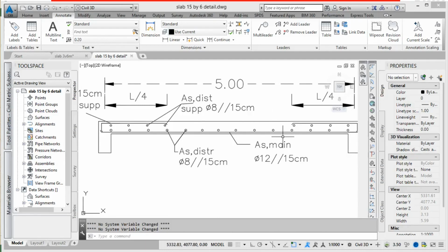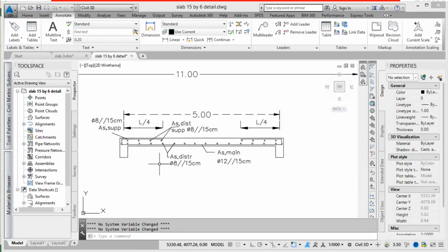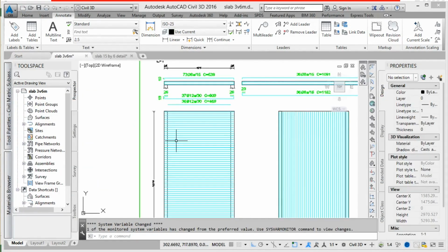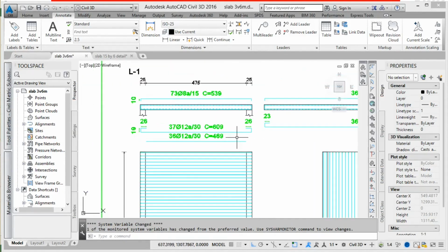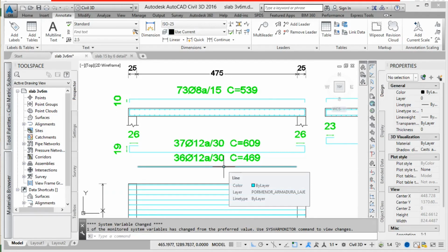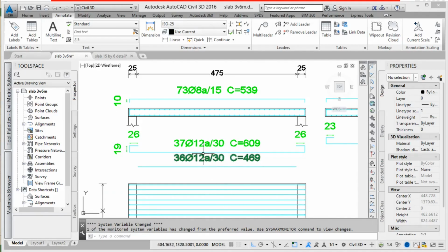For economic purposes, if you can guarantee there will be no traction here, this is the ideal reinforcement, as we can see in this calculation in a software whose name I will not say. What they did is exactly that: our diameter on the bottom is 12, and in the detailed way it's spaced here by 30, and we calculate it by 15, so it is exactly the same.